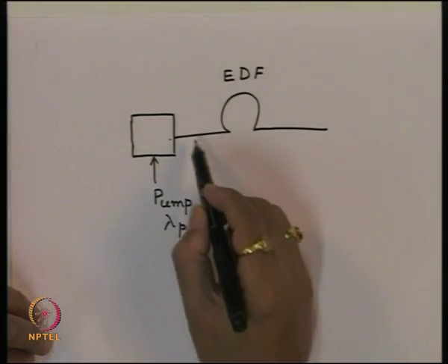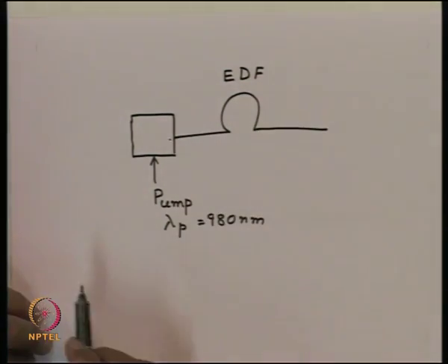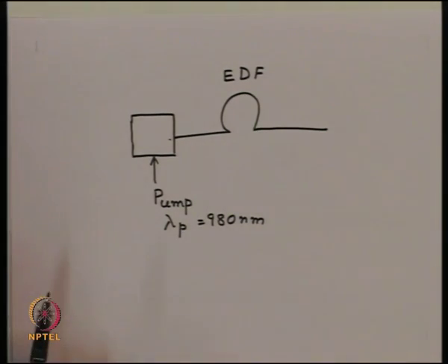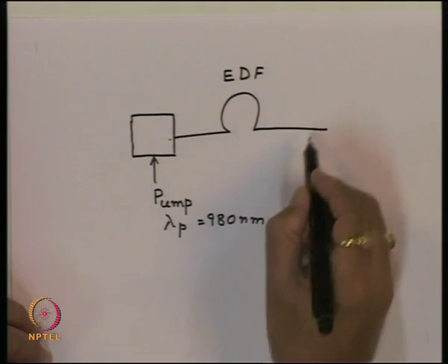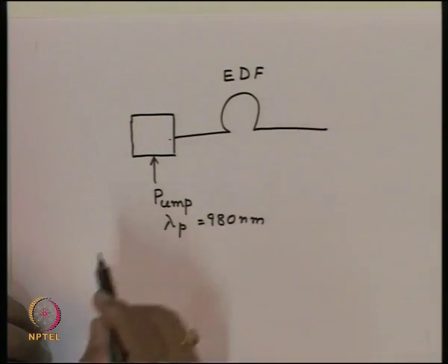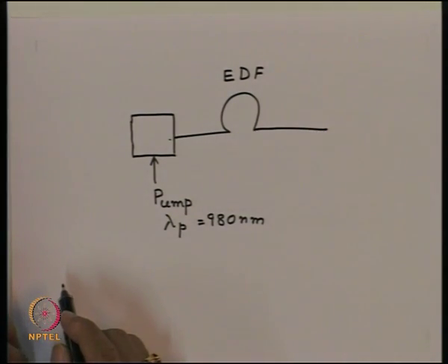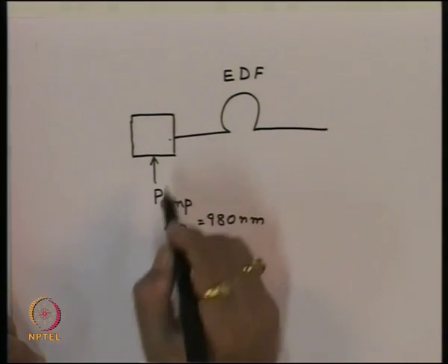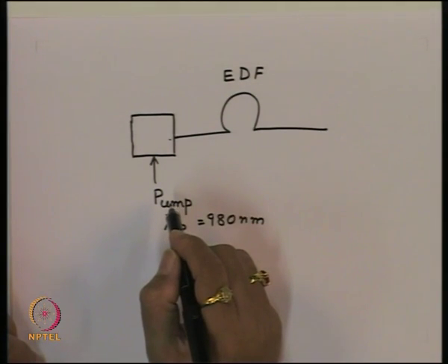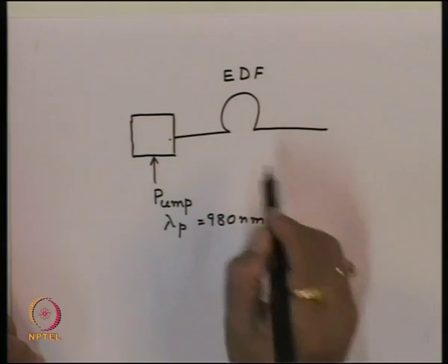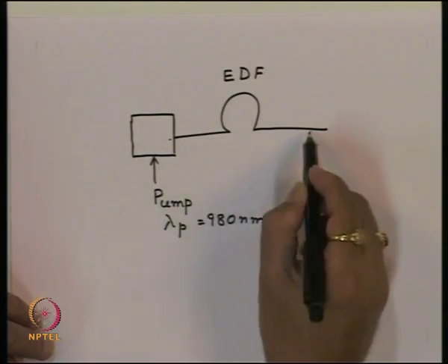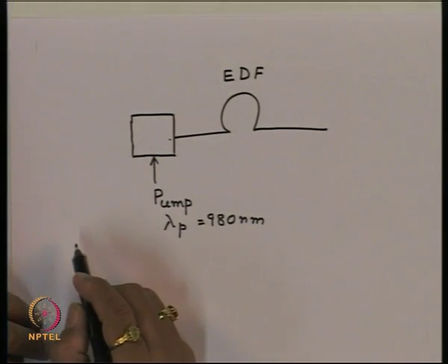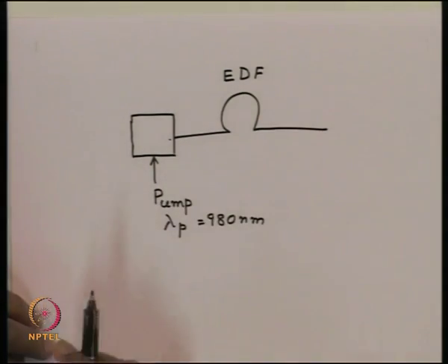Now, since we are having a medium here which is amplifying, and the gain of this amplifier is very large, even a small reflection because of any deformations in the fiber or something may have a feedback, and since the gain is very large, there is a good possibility that this signal which is fed back because of small reflections, it may put this whole device into oscillation.